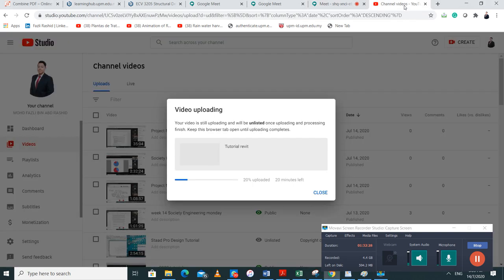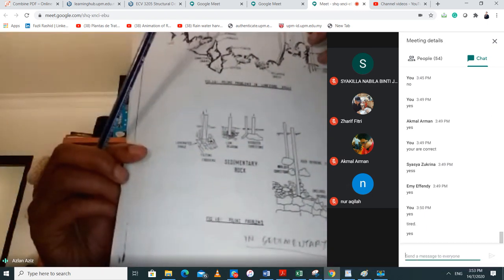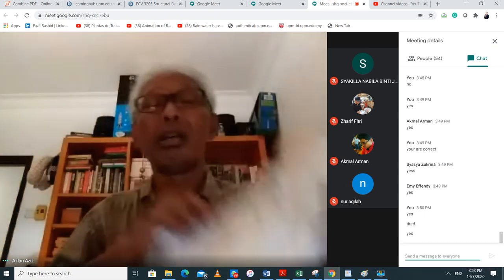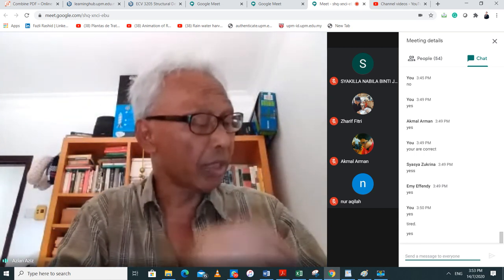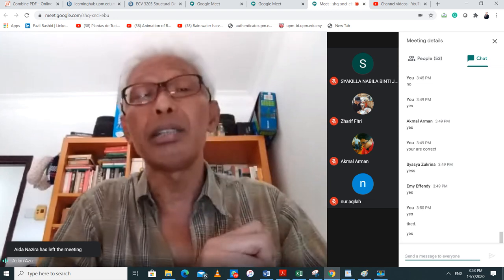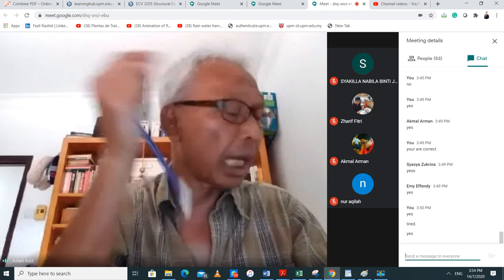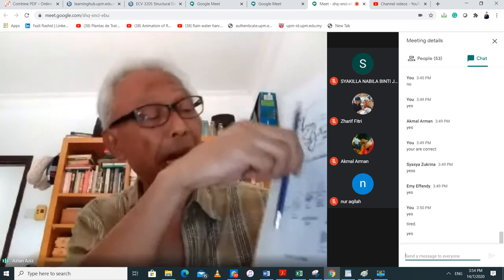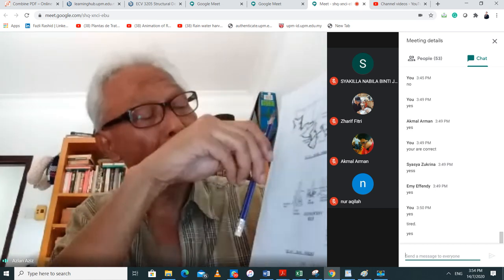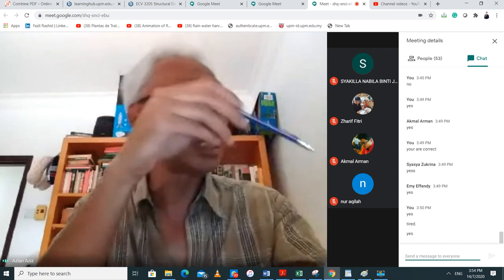So you have this one here, sedimentary rock. If you are in the Kuala Lumpur area, you have to deal with all these things. So apart from the limestone, you may have this problem in the sedimentary rock. You have that laminated shale. The shale tends to erode with time and at an inclination. See the inclination here? So you drive the pile and then it wants to go that way along the alignment of the laminated shale.